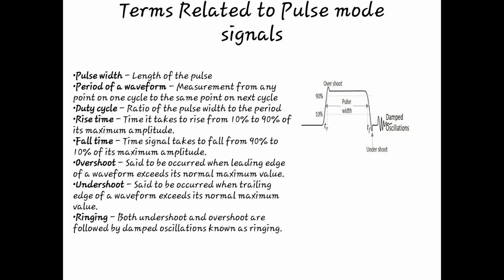But in the case of fundamental mode circuits, the input changes should be spaced in time by at least delta t, the time needed for the circuit to change its state. That is, the input variable should change only when the circuit is stable. Only one input variable can change at a given instant of time, and also in fundamental mode circuits, inputs are levels, not pulses. Delay lines are used for memory elements.